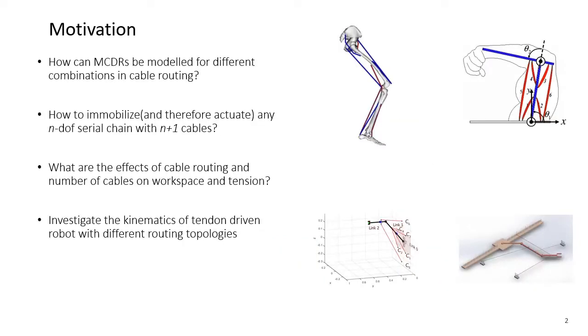In recent years, there has been an increasing interest in robotic and other mechanical systems actuated or constrained by cables. In such systems, an individual constraint is applied to a body of the mechanism in the form of a pure force, which can change its magnitude but cannot reverse its direction. The unidirectional actuation complicates the design of cable-driven robots and can result in limited performance.